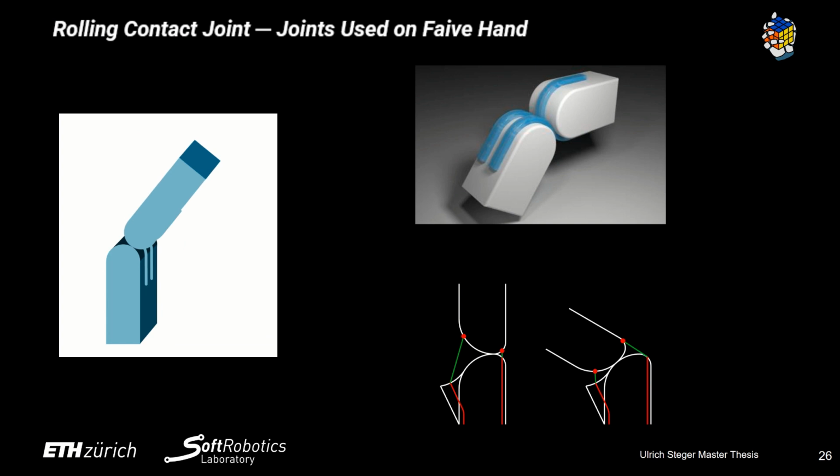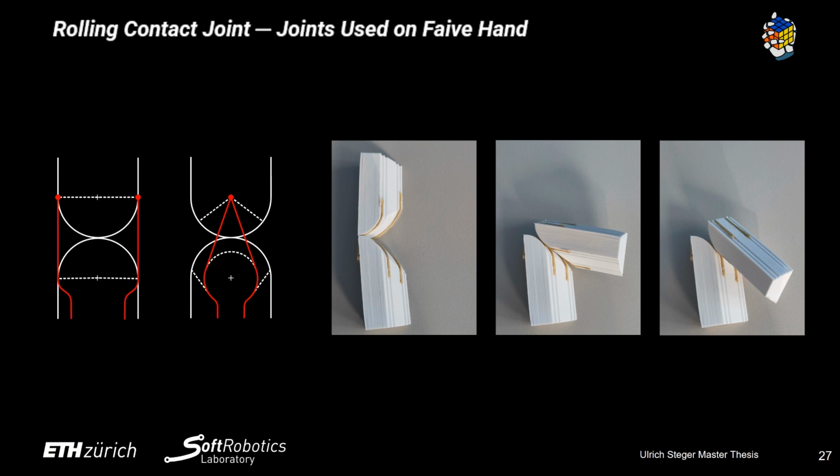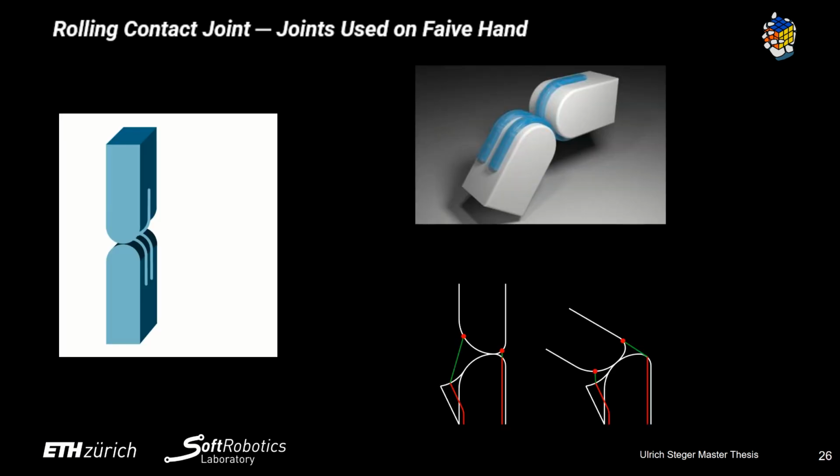So for robotic hands like the 5-hand, all joints are rolling contact joints, which means they do not have a fixed axis of motion. The rolling contact joints on the 5-hand are controlled by tendons, and we assume they are not being stretched. So, as the length of the tendon channels inside the hand does not change, the length of the exposed tendon should not change either, and could be used in the dynamics control of the 5-hand.